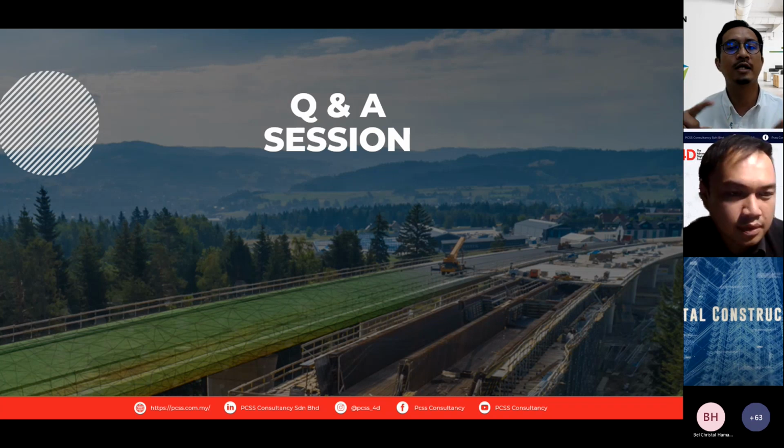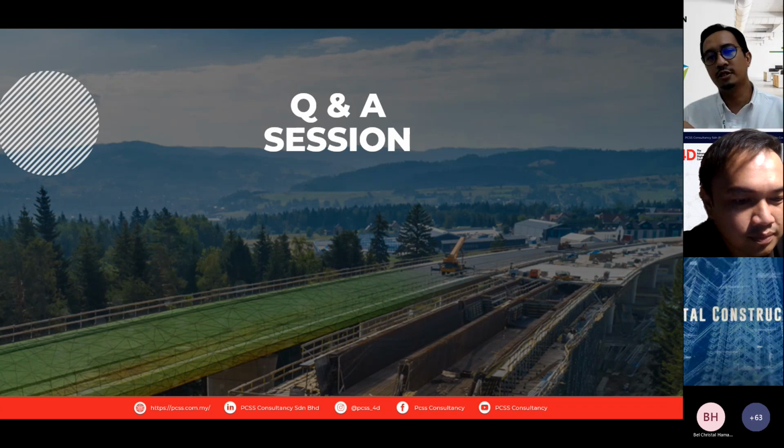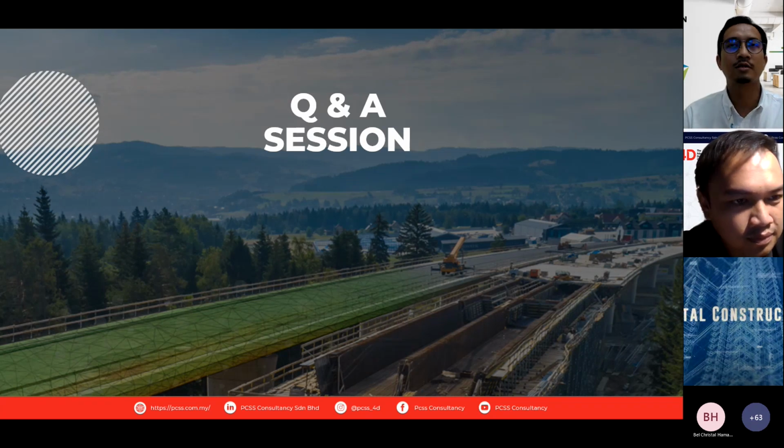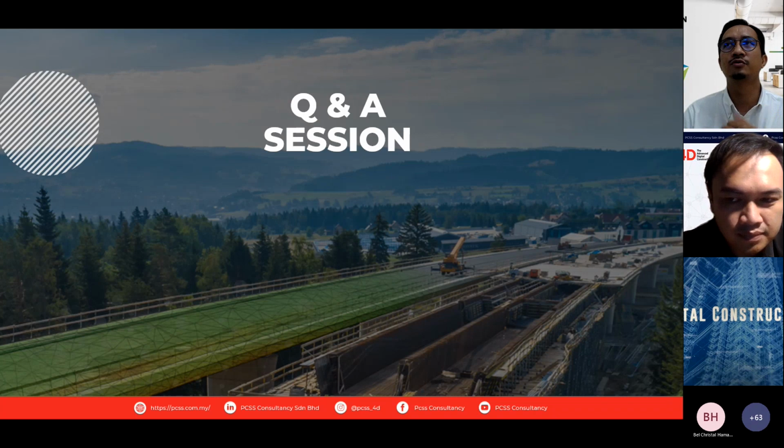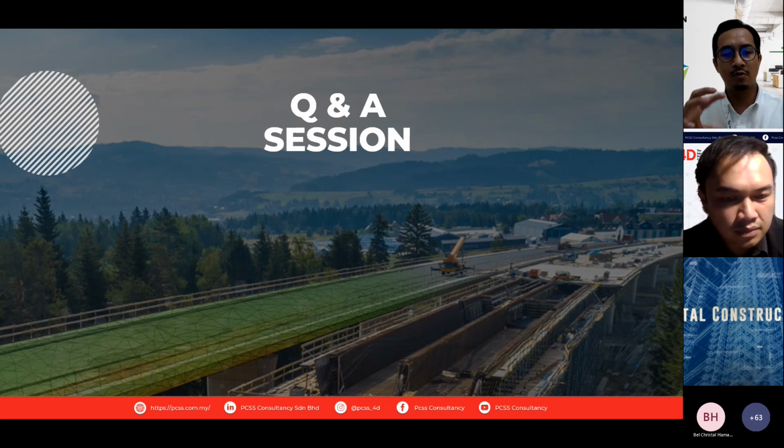But we also look at deliverables. Are you going to model it in BIM authoring tools? Are you going to just mesh it? Or do you just want a very detailed point cloud data? With a 2 million points per second technology, it will be quick because the coverage is bigger. You can have more points, you have more details.